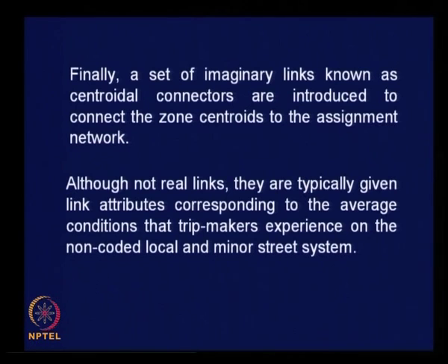Although not real links, they are typically given link attributes corresponding to the average conditions that trip makers experience on the non-coded local and minor street systems. There are several local minor streets which feed traffic onto the main roads. These imaginary links represent the traffic flow on all the minor roads within a traffic zone, right.